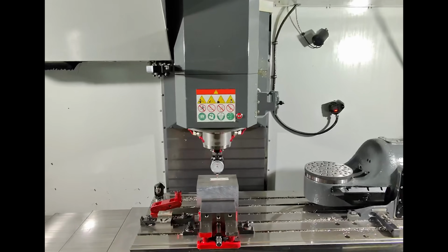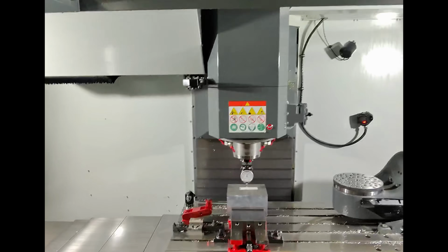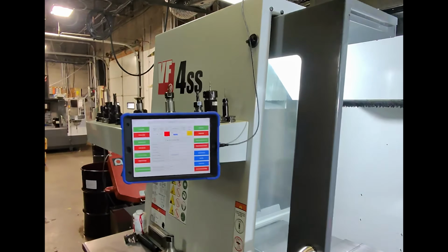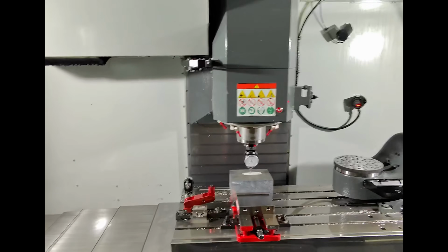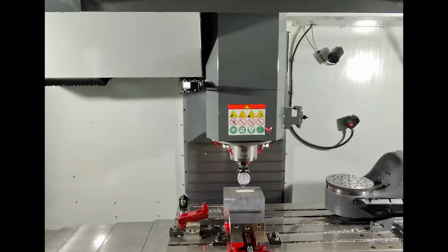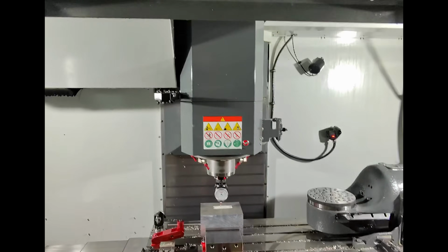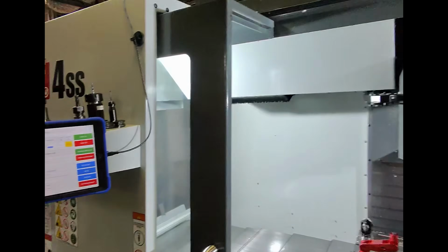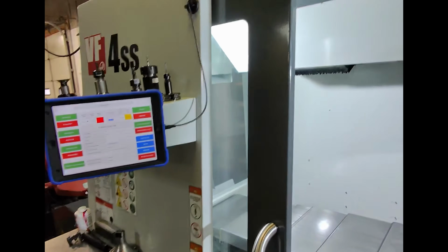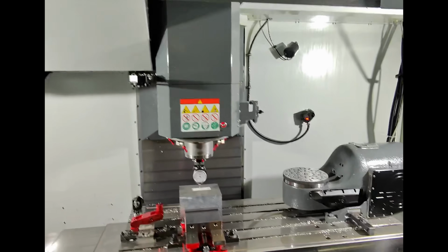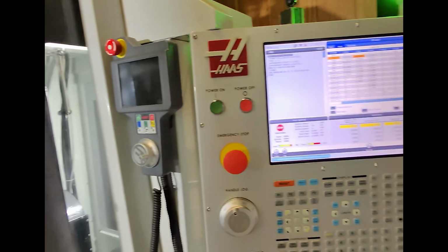Okay, so now that I've caught the XY 0 position, I can go ahead and run my program. And the way we do this is while still in setup, because we don't know the current cycle time yet. Yes, the CAM software tells you the approximate time, but it's never very accurate. It all depends on the machine. So I always run the first part while still in setup mode. That still gives me a very accurate time on how long it took me to do the setup.